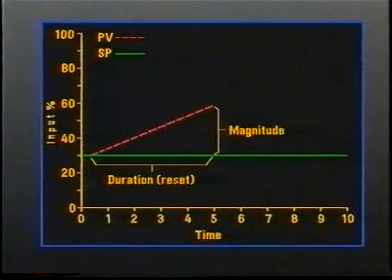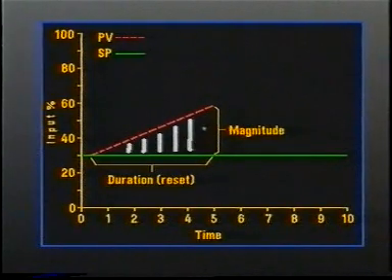If the gain setting provides a signal that does not fully correct for the error, then the amount of remaining error will continue, since the controller cannot tell that it exists. Integral action addresses this problem by providing a repeat of proportional action on the error. The frequency of these repeats is called the reset, and its effect is to make it possible to avoid a continuing error by continually correcting it until it reaches zero.